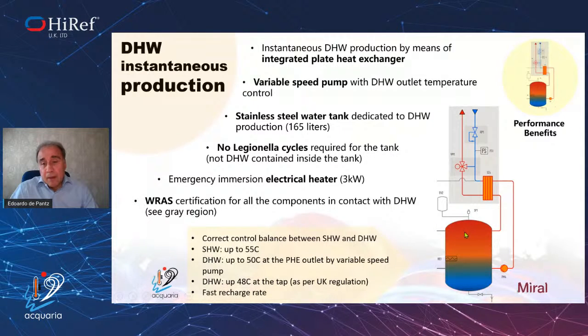In the tank we typically have 55 degrees in order to have 50 degrees at the outlet of the heat exchanger, and then 48 degrees at the tap, as per the UK regulation.